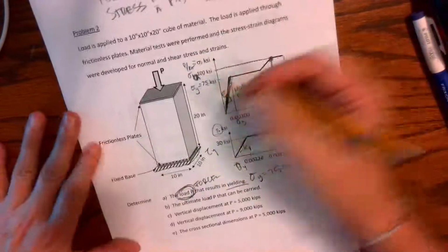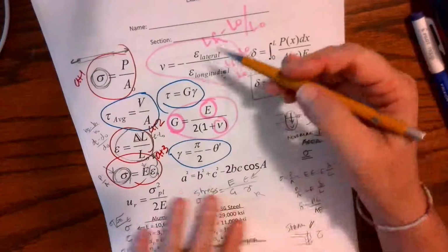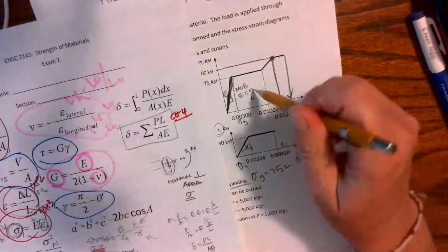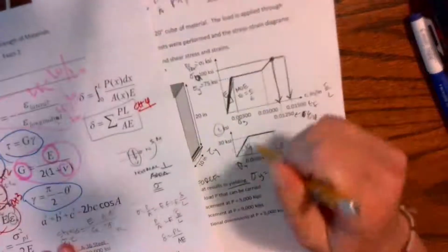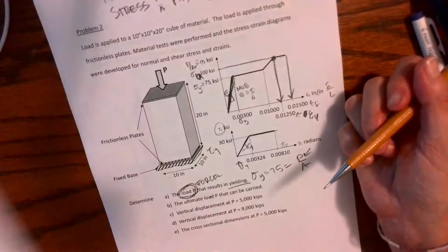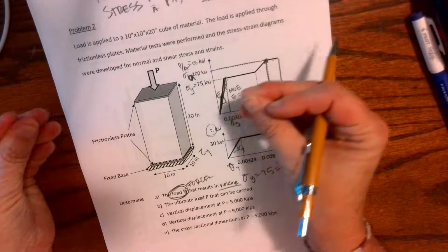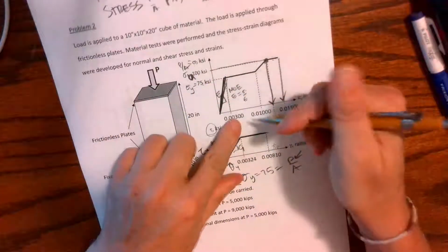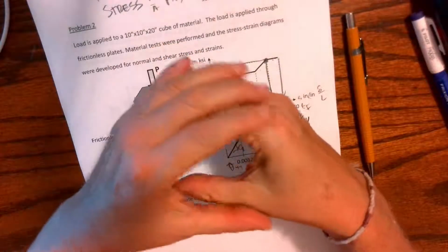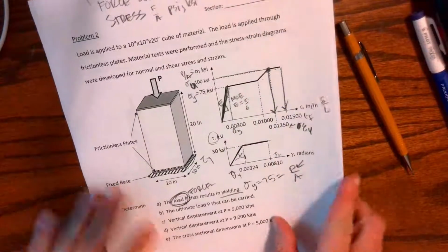If I wanted Poisson's ratio, I have that. You have to understand, well, what is Poisson's ratio? How can I find it? Poisson's ratio is this funky little V. If I can find E, which is the slope of my normal, and G, which is the slope of my shear, then I can calculate Poisson's ratio. Okay? And that relates my stress that makes something longer. It then relates that strain, that change in length of getting longer, to the change in length of the diameter getting smaller, or the diameter getting bigger if I'm in compression. It's just relating the geometry of my area.